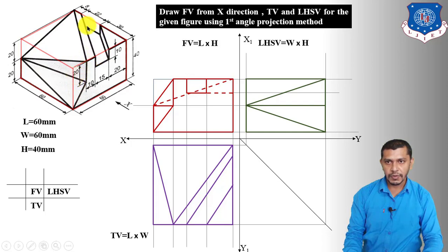So we have to draw this part which is going to be hidden. Project this part from the top view. So this is the opening of the slot at the back face. Project this like this. So here we will get a rectangle of the slot like this over here. It will be hidden. The 22 mm edge is also going to be hidden over here, and then after this, the line is also going to be hidden up to this corner point. So we have to draw a hidden line like this.